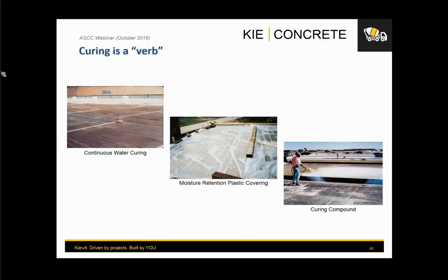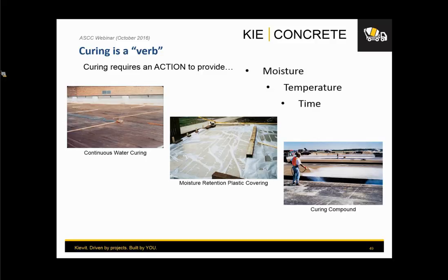Now, the other thing that we always have some type of challenge communicating and making sure that we implement right in the field is curing, right? And curing, I always make it very, very clear: curing is a verb. Curing doesn't happen just because you dump concrete and then the concrete is going to do it itself. Curing requires an action. It requires an action to provide adequate moisture, adequate temperature, adequate time.